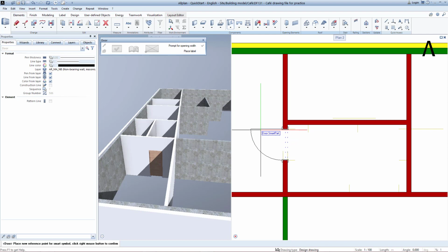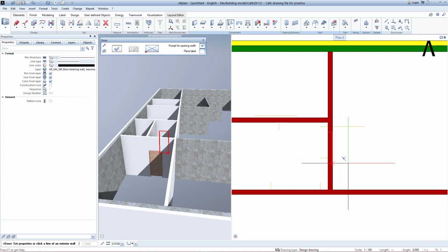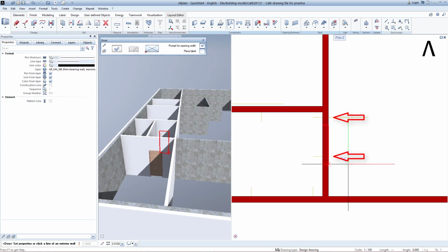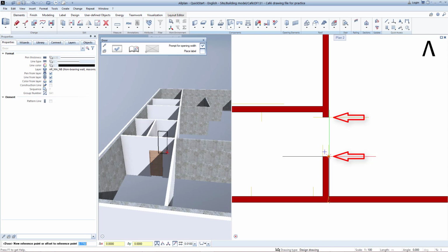By left-clicking next to the wall in the direction of the 4 now possible stop directions, I determine the direction, decide on it, and close the doors by pressing Escape. The door function itself is still active, and since I have to create more doors, I do this now, and you see I can of course enter this directly at this desired place if the position of a door is already fixed by means of extension lines.